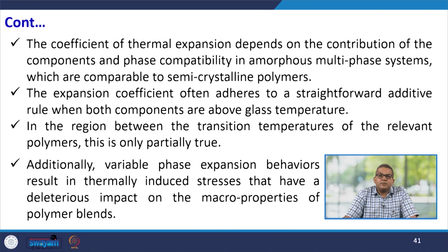The coefficient of thermal expansion depends on the contribution of the components and phase compatibility in amorphous multiphase systems, which are comparable to semicrystalline polymers. The expansion coefficient often adheres to the straightforward additive rule when both components are above glass transition temperature. In the region between the transition temperatures of the relevant polymers, this is only partially true.